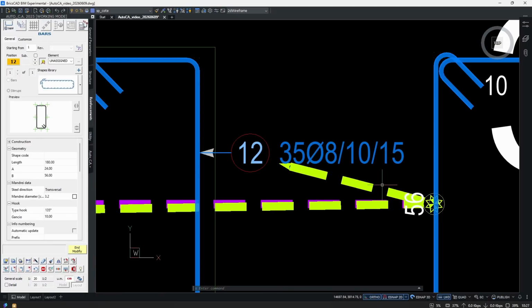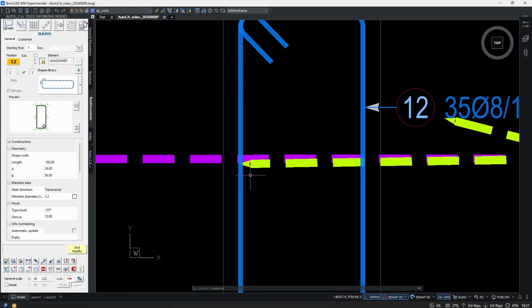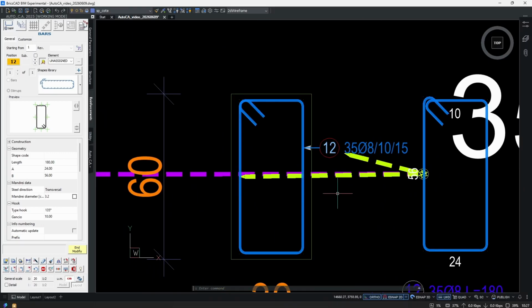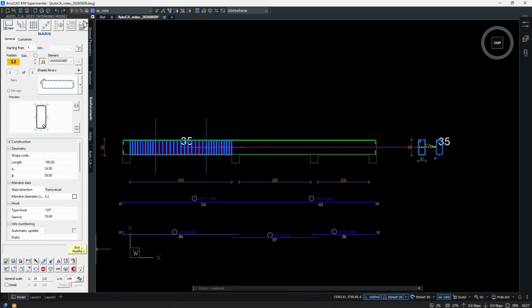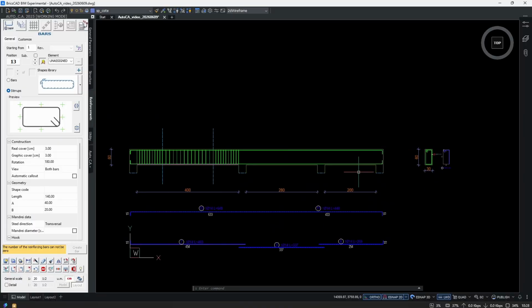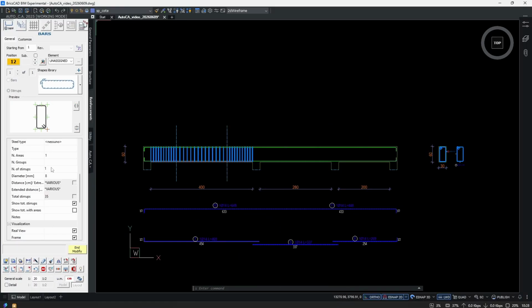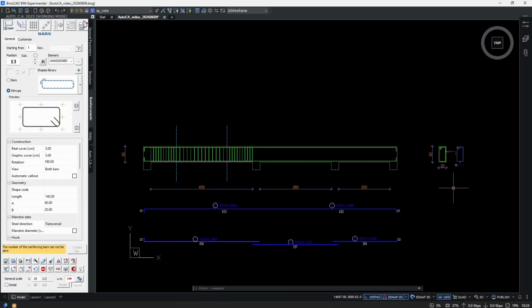The callout is also linked to this bar, and the inside bar is linked as well. So this is the correct way to use the program logic to count bars. Yes, there's the possibility to insert bar number by hand, but it's always easier to let the program do the hard work. And most of the time, it's more precise also.